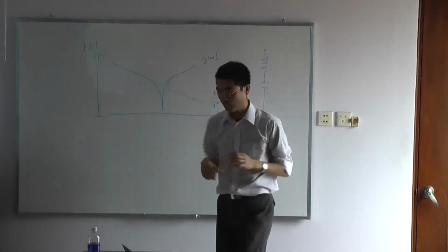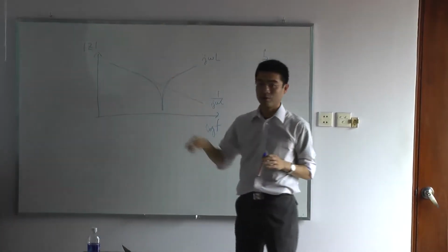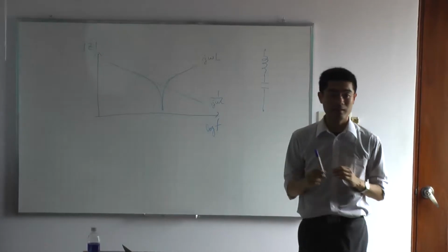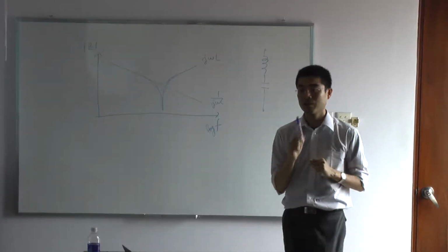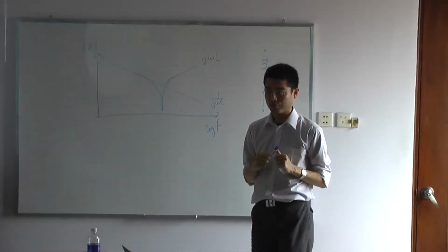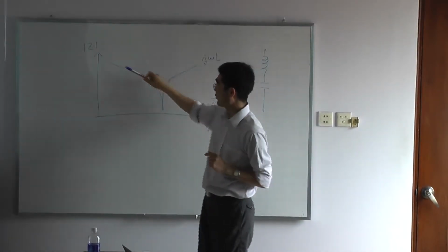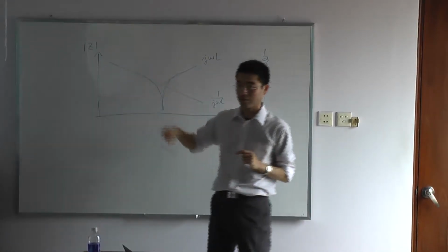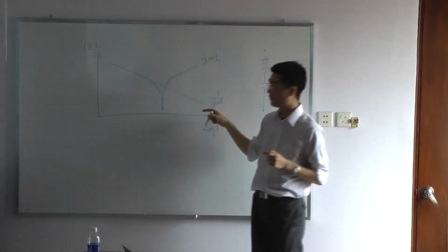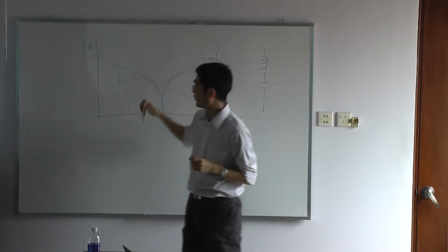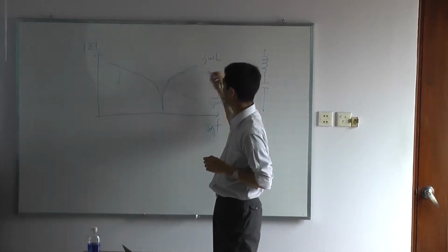So from the power supply noise suppression point of view, we want less impedance on the power supply. Ideally, we want zero impedance on the power supply. However, the line always comes with capacitance, resistance, and inductance, so we cannot make zero impedance. So we put capacitance and we want lower impedance. In order to do that, we want to put a larger C. The larger C will bring down the impedance, and a smaller L will bring down the inductance like this.